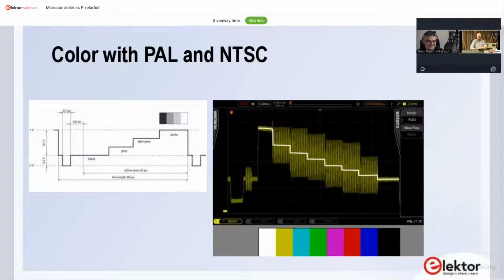Yes, definitely. And I mean, NTSC is also sometimes called never the same color. If you had a small shift in the signal, your skin tone would get greenish, and your green palm trees would get pink and that sort of stuff. That's later on solved. That's why NTSC TVs have that tint control and PAL TVs don't. Yes, PAL has some trickery in it that makes at least that not visible to the eye. The picture will get less sharp, but yeah. Or less saturated. Yeah, but you have to pay another license.